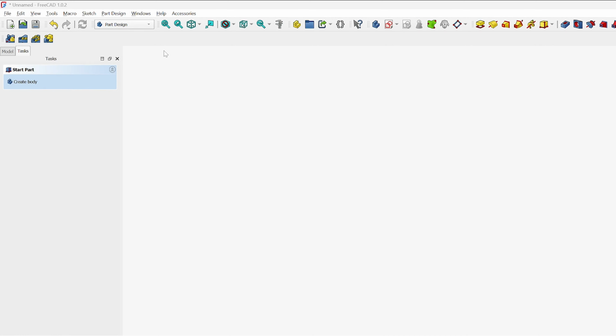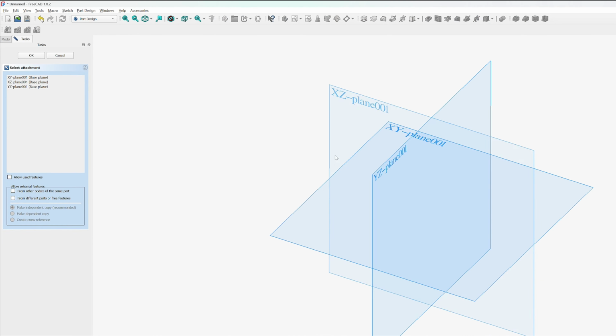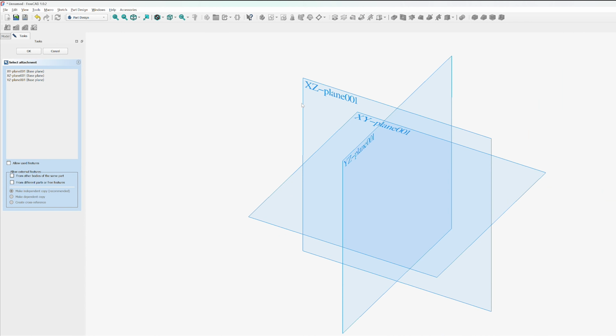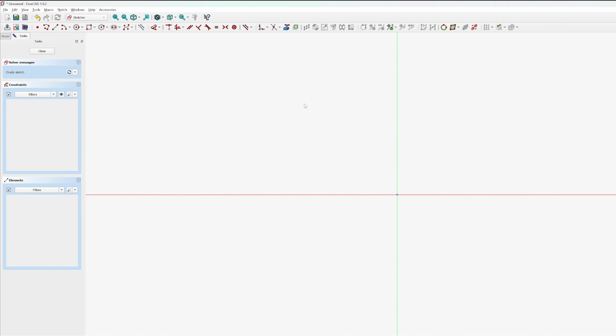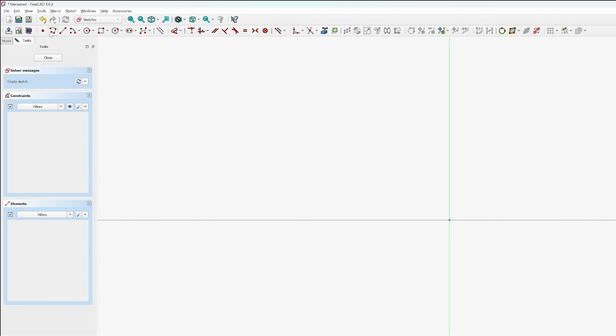In order to jump into Sketcher, here I am in the Part Design environment. Here I'm going to click on body and then create a body required sketch. Now let me quickly take any plane. Let's say I have taken the XZ plane. It's up to you what you want to call it. And we were just discussing these different tools that are available inside Sketcher.